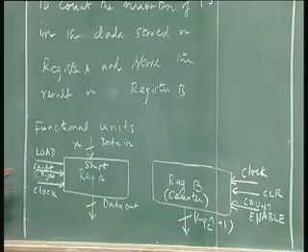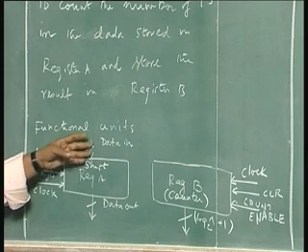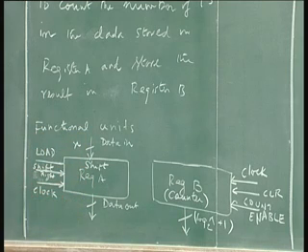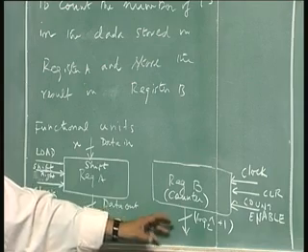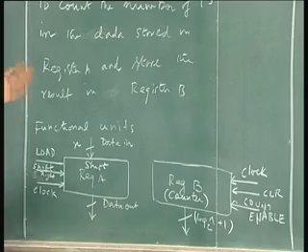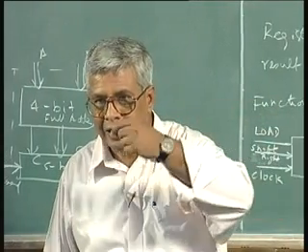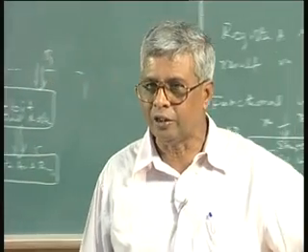So right now I am saying a register which has a shifting possibility and loading possibility, whose data in and data out available is what I need for A. For B, I need a counter which can be cleared to start with and enabled whenever we want at the edge of a clock, and then the output should be read as parallel out. Finally, the result will be out. How am I going to use it? I will start my state graph, and then when the nitty-gritties of the signals are available, if something is not available, I have to go back and make a little modification of this.